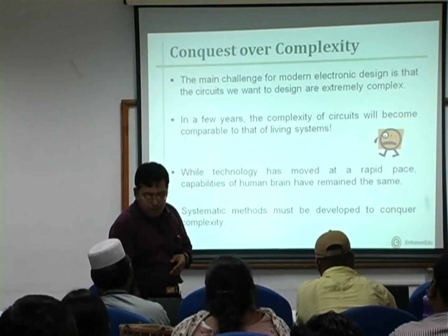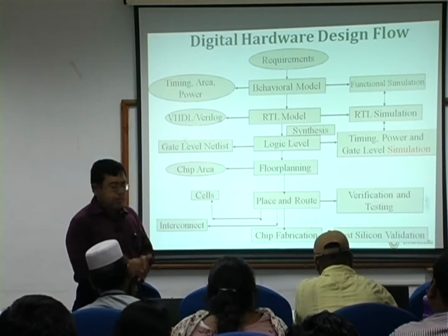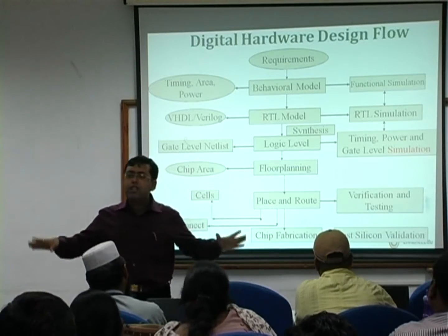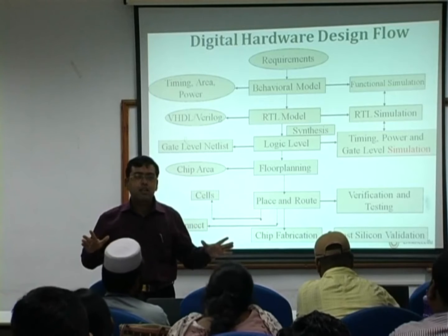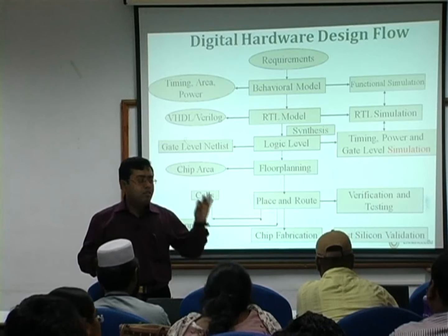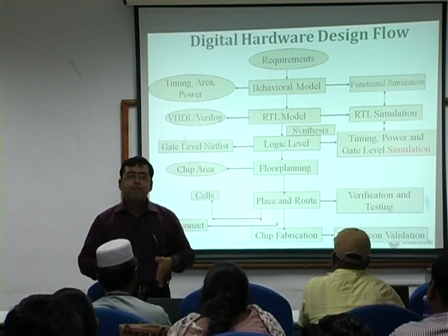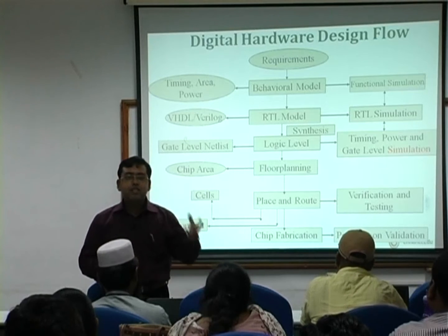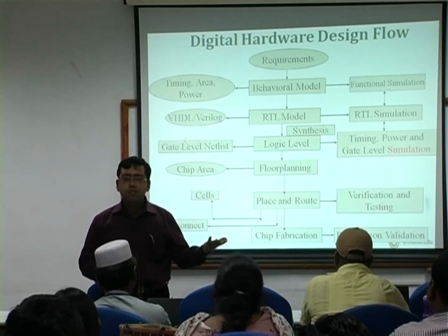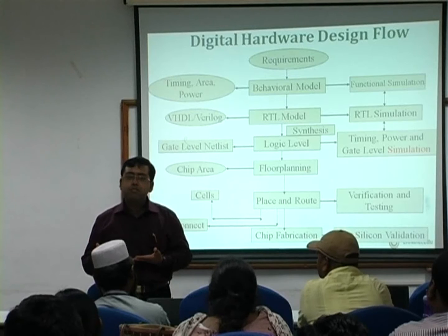Now after the chip is fabricated, another important thing is post silicon validation. You have ensured that the entire circuit is working, simulation results are perfectly okay, you have generated your GDS2 file, which we normally send to an industry for fabricating the chip. After the chip has been turned out by the industry, you go to some testing lab, you test the chip,